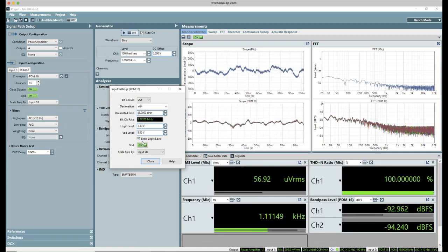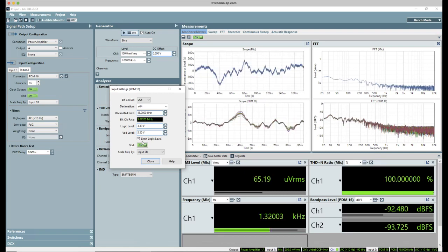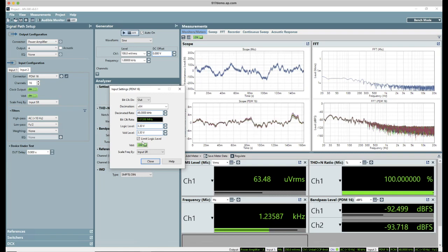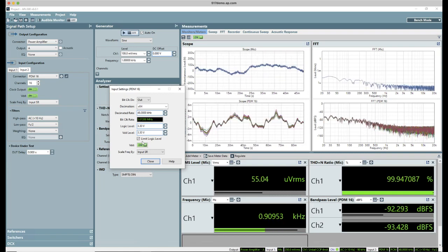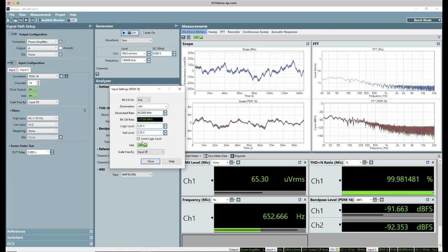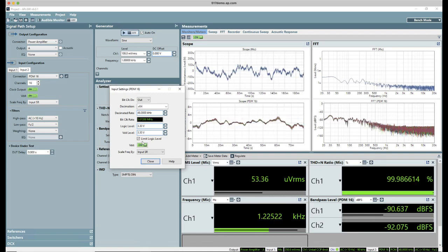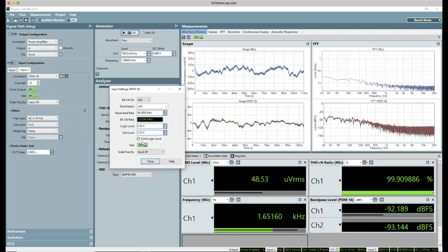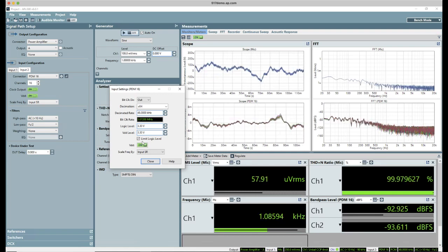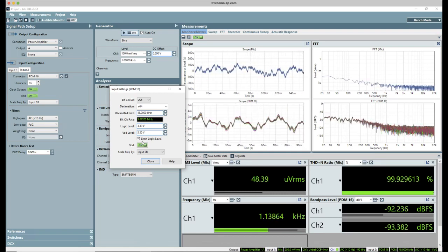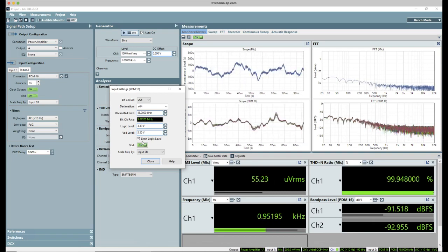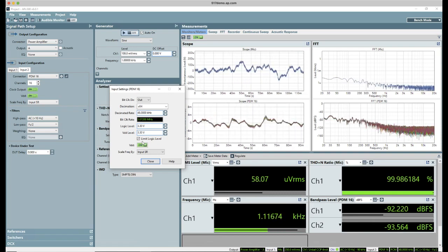a MEMS, a PDM signal, a pulse density modulation signal, is basically the raw output of a sigma delta modulator. I won't go into the whole explanation of that, but the quick and dirty of it is that it's a 1-bit A to D converter, as bizarre as that might sound.